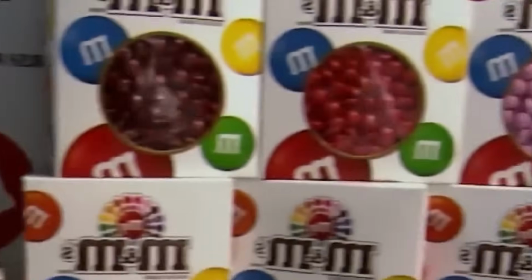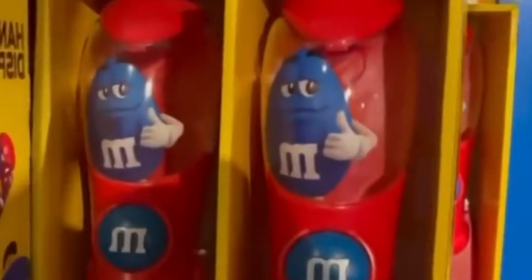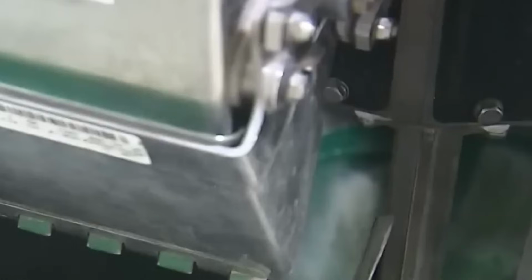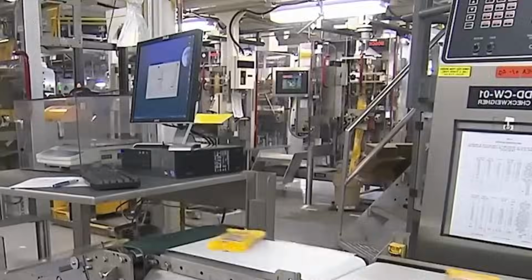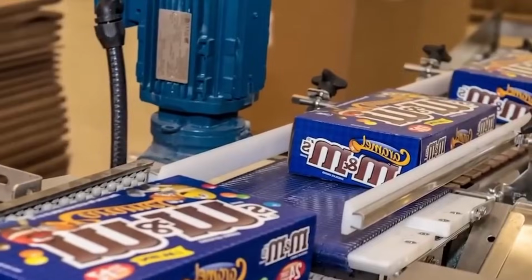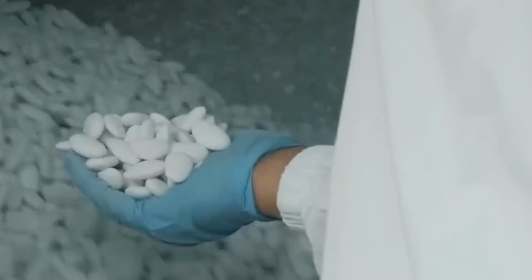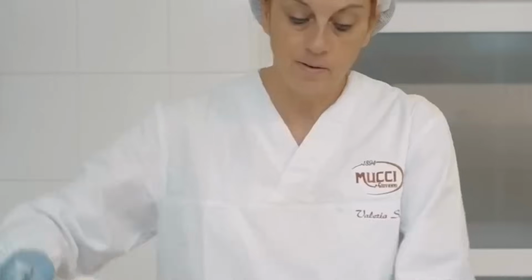The cooled caramel mass is sheeted and cut using a rotary cutter and high-precision die system. The sheeted caramel slab is passed through gauge rollers to reduce thickness and fed into a rotary die cutting unit where small square or rectangular cores are punched out. The cutting system operates in synchronized alignment with the conveyor speed to avoid misshaping.